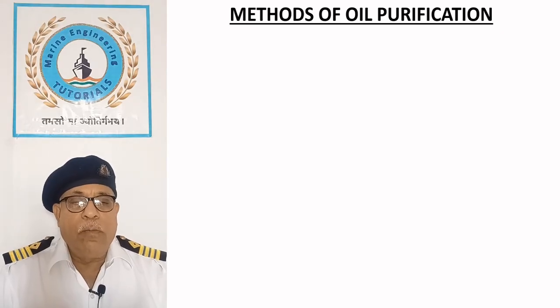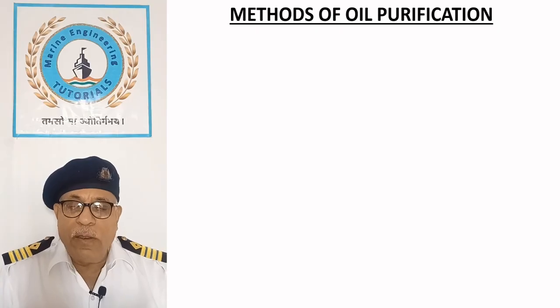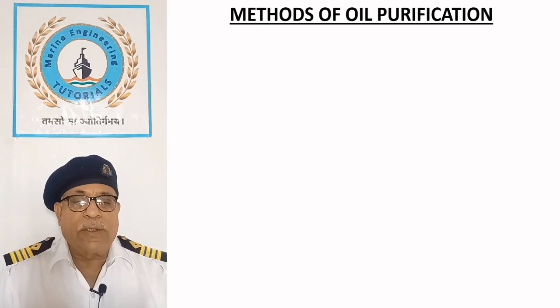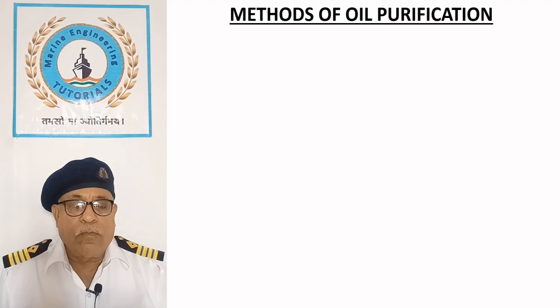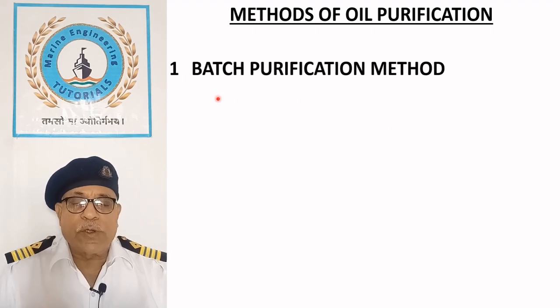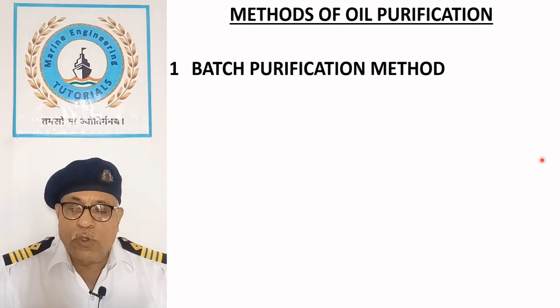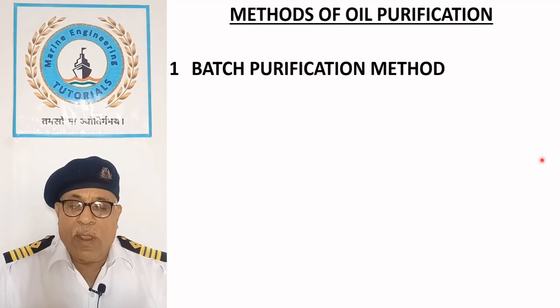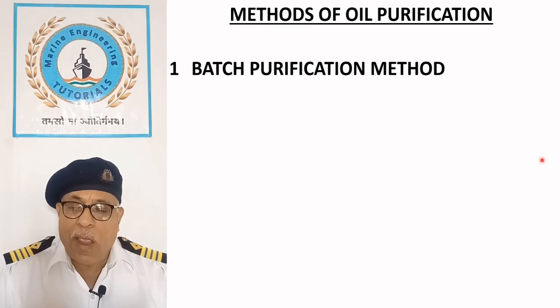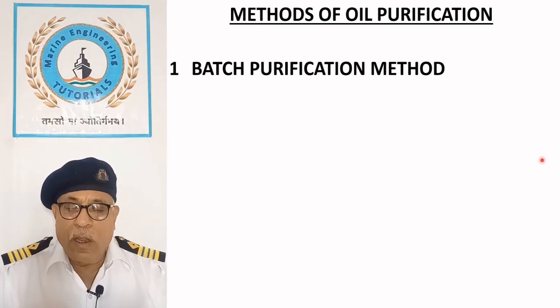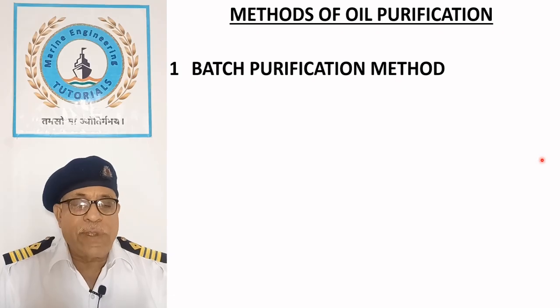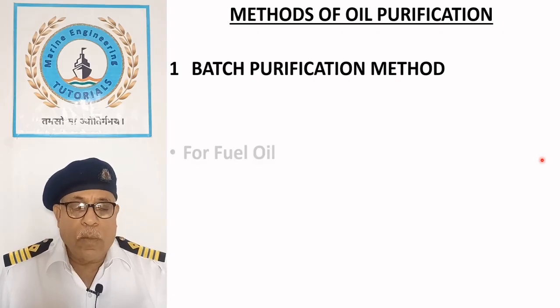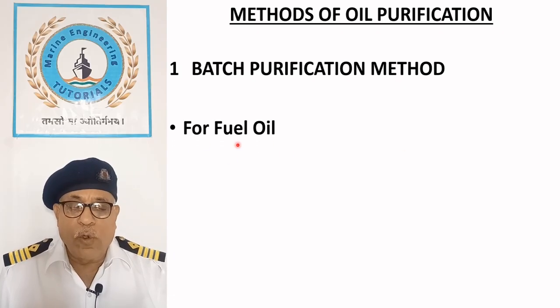Methods of oil purification. Oil can be purified by one of the following methods. Batch purification method. This method is mainly used for the purification of fuel oil, where the complete oil is passed through the purifier before it is supplied to the engine. For fuel oil.